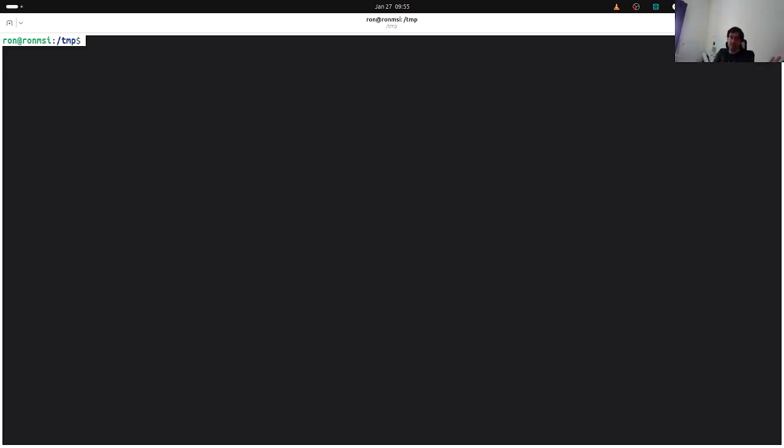This is actually what the AML flash tool does. So it flashes the bootloader, you can do it yourself. And this bootloader also recognizes that it's in a burn mode, USB burn mode, and then it receives all kinds of USB commands as we saw earlier. So that wraps it up.